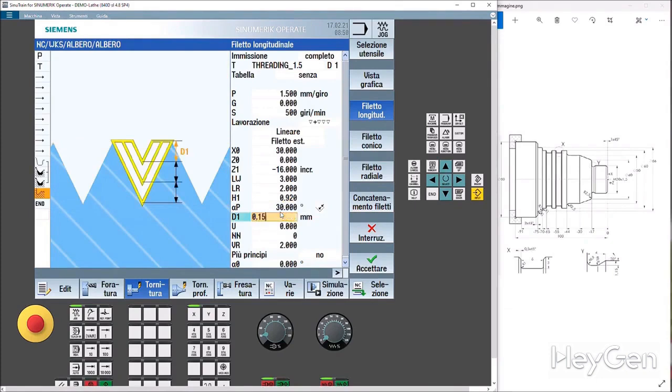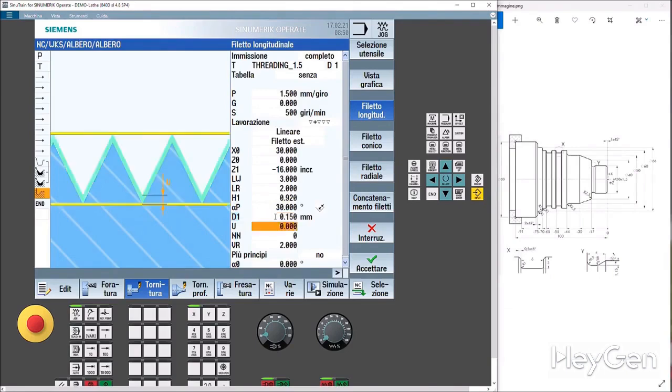All right, what do we have left to do? We have to make the 2 grooves. So we go to groove turning. Here it is. Let's select the tool right away. You see, once you understand the concept, they're all the same. We have a tool for external grooves, thickness 3, and the tip radius is 2.